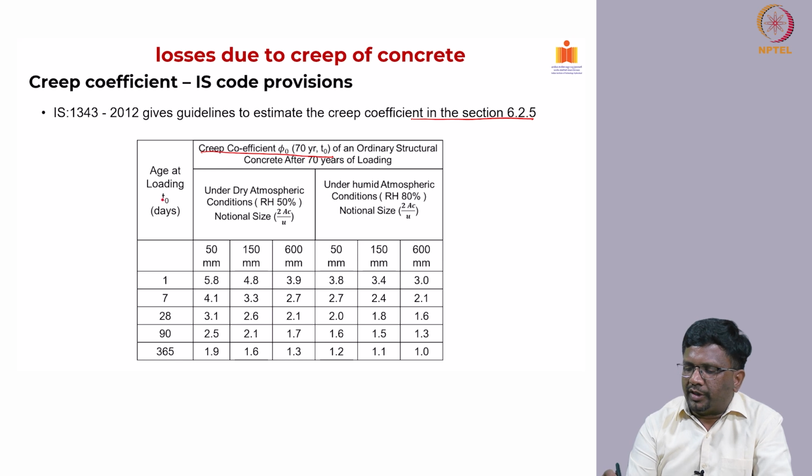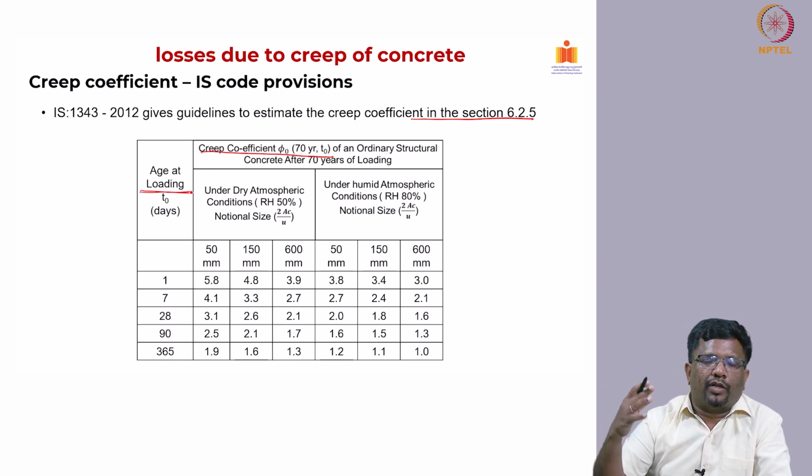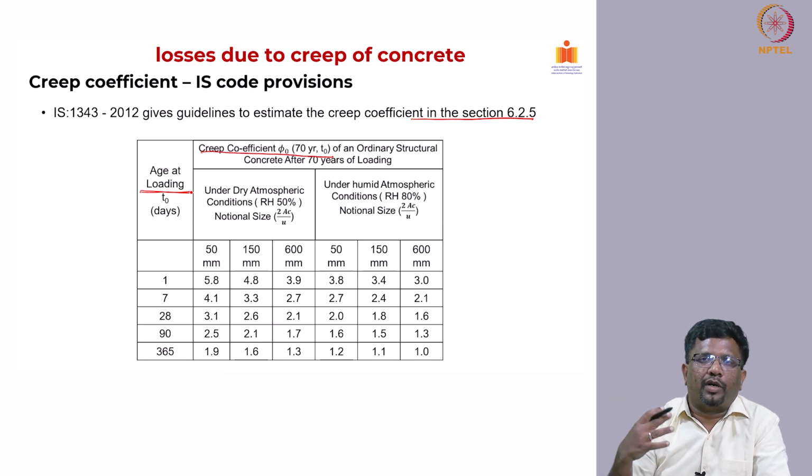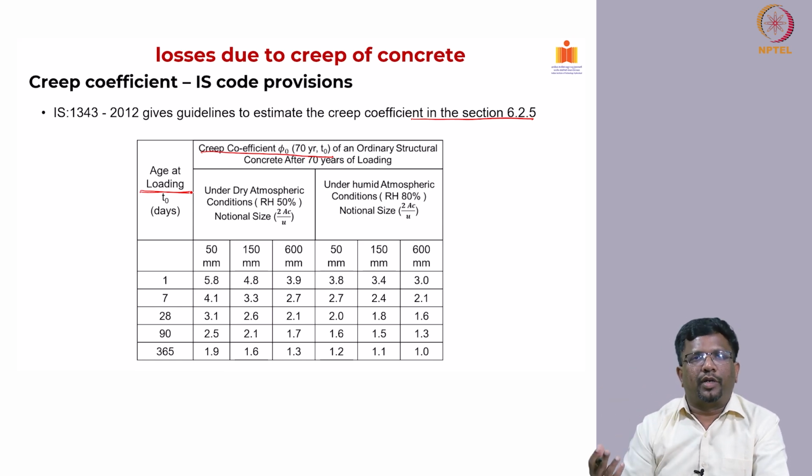Now here you can see it is also a function of the age of loading. Again we said when the curing has not happened properly, when you start loading the member at an early age, then the creep will be higher, right?